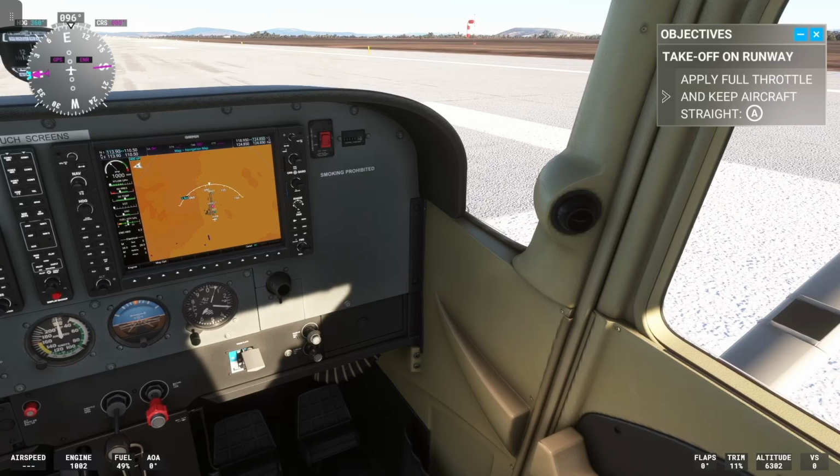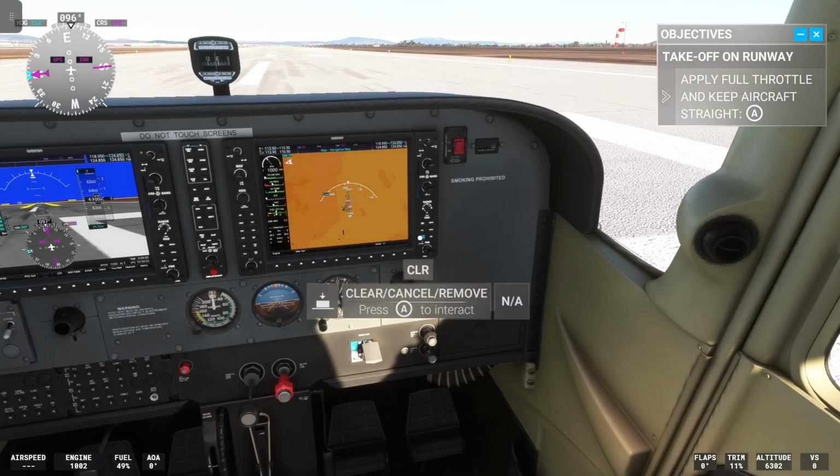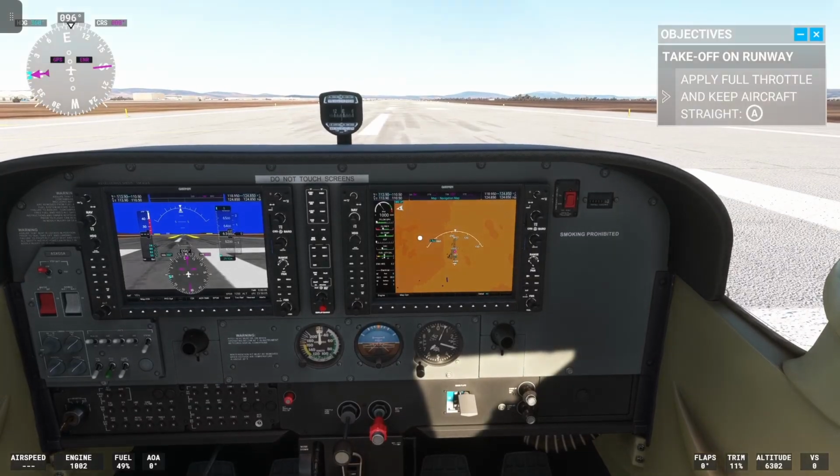And now from here we do traffic and clearance. So it would sound something like, if this was JFK, this is a desert airport, it would be something like: JFK International, this is Cessna 172 on runway 09 ready for departure. Now that would be based on this scenario. Ideally you'd be communicating this from hangars and you'd have a flight plan and you'd know even where to taxi. So even where you move on the tarmac is controlled.